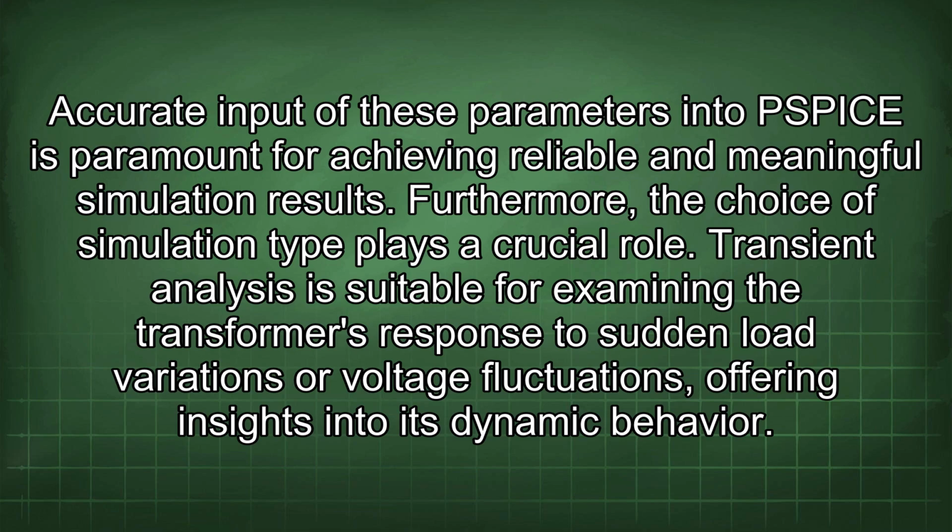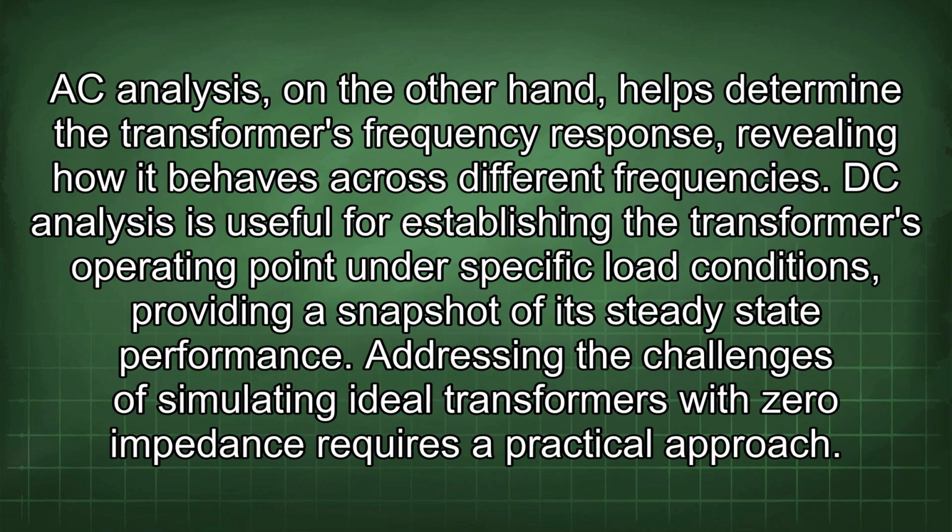Transient analysis is suitable for examining the transformer's response to sudden load variations or voltage fluctuations, offering insights into its dynamic behavior. AC analysis, on the other hand, helps determine the transformer's frequency response, revealing how it behaves across different frequencies. DC analysis is useful for establishing the transformer's operating point under specific load conditions, providing a snapshot of its